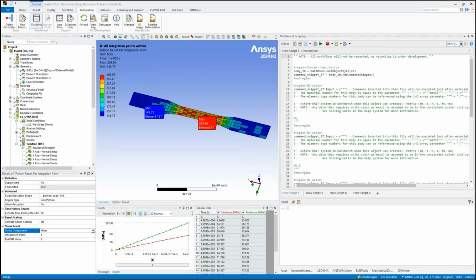Now, more recently, in recent versions of Ansys, I think it's 2022 R2 on, we now also have access to CPython. CPython is probably the Python that you may be familiar with, downloading from python.org. Using that capability, and we'll see that later on, gives us the ability to call in external functionality to use some of the advanced data processing or numerical libraries like NumPy or SciPy. Having that capability really does enhance some of the offerings that we can then customize our Mechanical with. For example, I'll show you an example later on of a composite fatigue calculation that I've encoded using an external Python library.